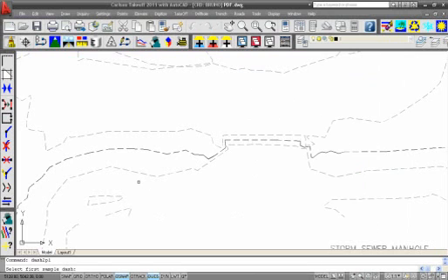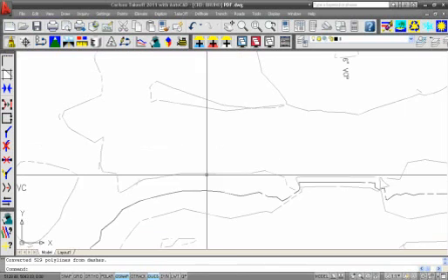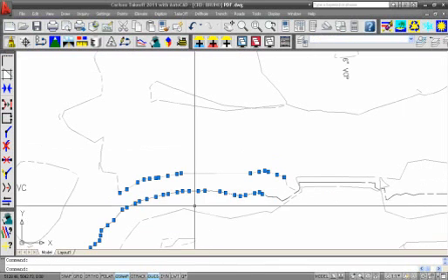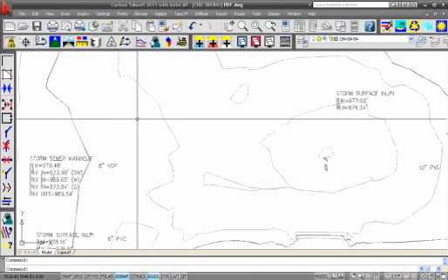It asks me for a sample of the dash. So let's zoom in here. Select an adjacent dash line. This is so the program can approximate the gap between the line work, so it knows how to join it. And then it says what to process, and I'll type in all, enter. And now I get solid lines on a lot of that line work.